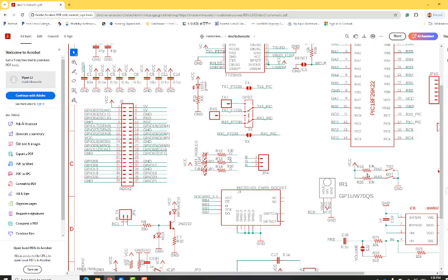Okay, picofarads is really huge. I was able to build like 20 picofarads capacitors on the chip. It's already taking like 30% of the area of the chip or the die. The little tiny integrated. For example, I can let you take a look at it actually.